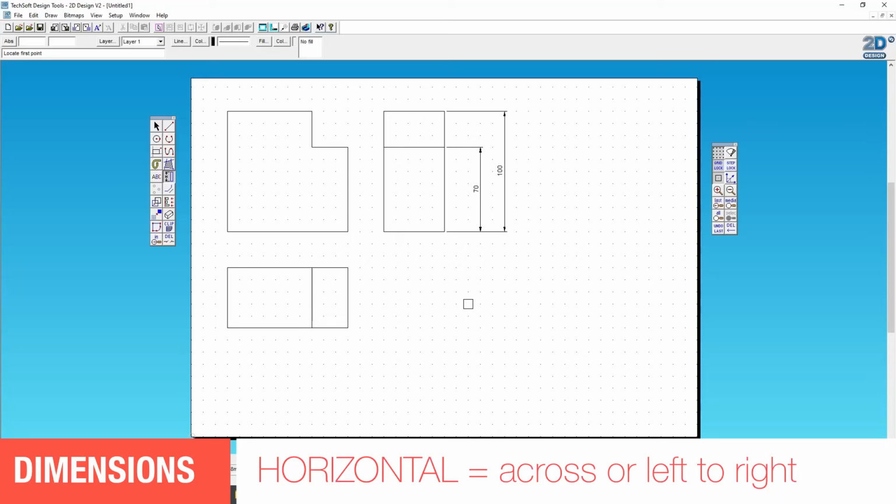The horizontal dimensions are drawn in exactly the same way, except you switch to the horizontal measuring. Make sure attach is on and click the lines that you wish to include in your horizontal measuring. None of the measurements should be inside the actual drawing.